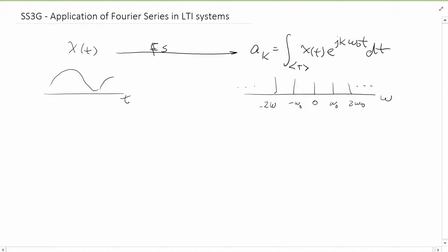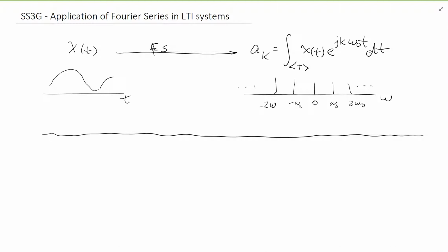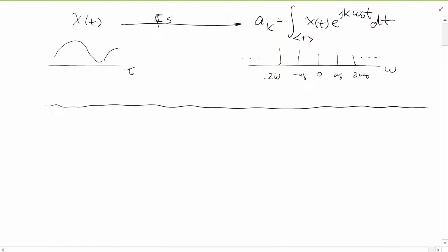Now, how do we use this? Sometimes it's useful to look at signals over time, but a lot of times it's useful to look at individual frequencies. For example, the reason the message coming to your phone doesn't get mixed up with the Wi-Fi, the TV or the radio is because your signal is being filtered. We could build a filter with capacitors, inductors or resistors, but if we translate our signals into a Fourier series or something equivalent, we can simply eliminate all the coefficients except for the frequency we are interested in, and therefore we are filtering it.